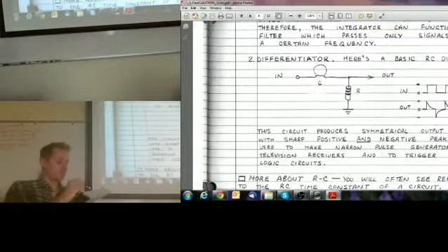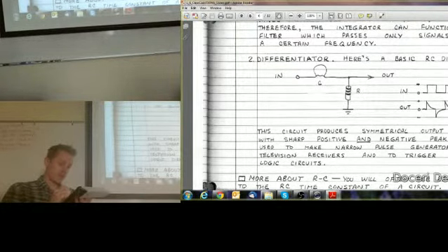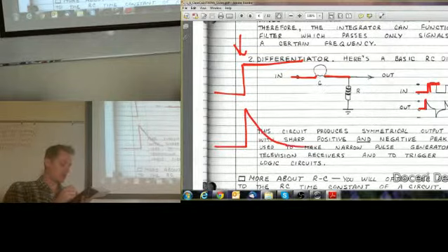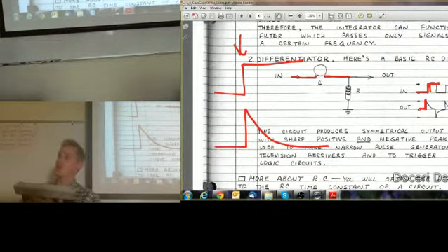So what does that mean? If a capacitor is configured in series here with this resistor, and the fast moving signal gets through the capacitor, that means the spike gets through. But then when it goes to this DC level, this is the fast moving part, so it tends to get right through. But the DC part of the signal, the capacitor tends to reject the slow moving or DC part. So eventually it's going to decay down to 0.